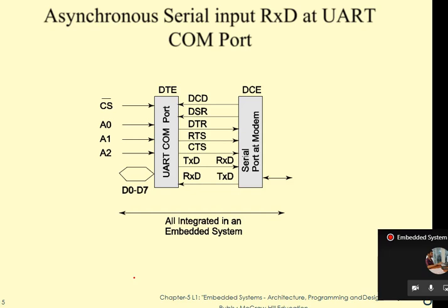Here if you see, you can't find the clock signal. So I'm not going to send using the clock signal. I told another methodology: I will send the data as a packet, or framed. So data will be there, and along with the data I will send the start bit, and in order to show the end of the data received, I will add the stop bit, and if I want, I will add the parity bit in order to check whether any error occurs or not.